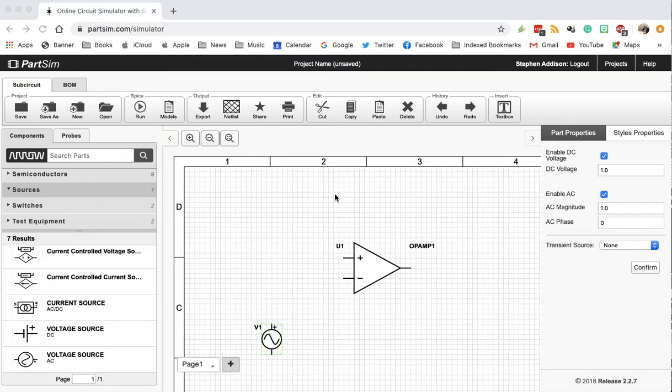Today I'm going to show you a quick example of one of the extreme cases of the non-inverting amplifier. I'm going to make a follower, and basically the way to do this is to make R2 be 0 and R1 be infinite, and this leads to an amplifier with a gain equal to 1. As you'll see, the input is exactly the same size as the output.